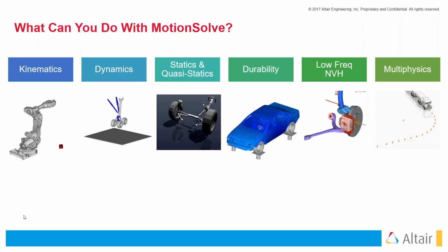The example shows a brake squeal application, which we can simulate using MotionView and MotionSolve. And we do multi-physics applications as well, where we can use controllers, tires, hydraulic systems, drivers and different tires. All these complex physics can be clubbed together and solved using MotionView and MotionSolve, and can communicate with other 1D codes as well. So that's about MotionSolve.